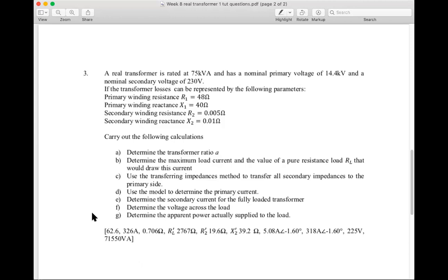It's drawn as a resistor, but technically you'd have to say it's an impedance because you're AC. So they're kind of interchangeable. If you're talking about pure resistance, you can interchange R and Z. But as soon as you combine it with anything reactive, like an inductor or capacitor, then it has to be Z, made up of resistance and XL and XC.